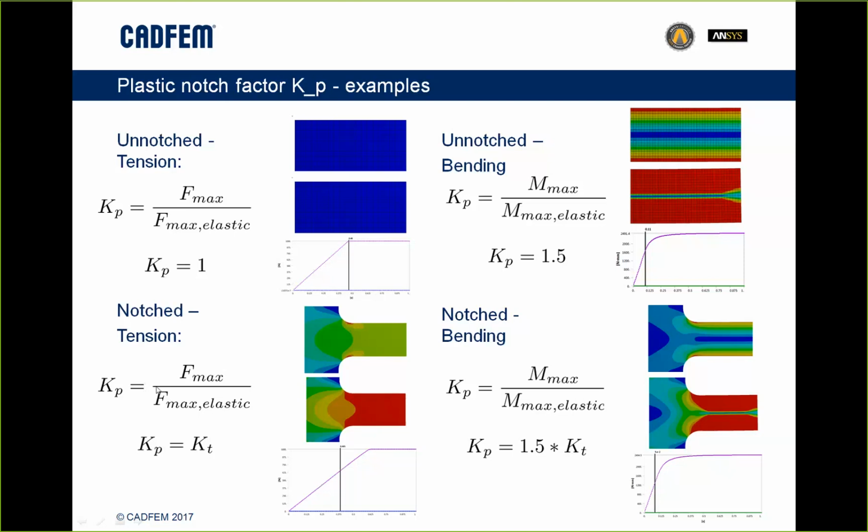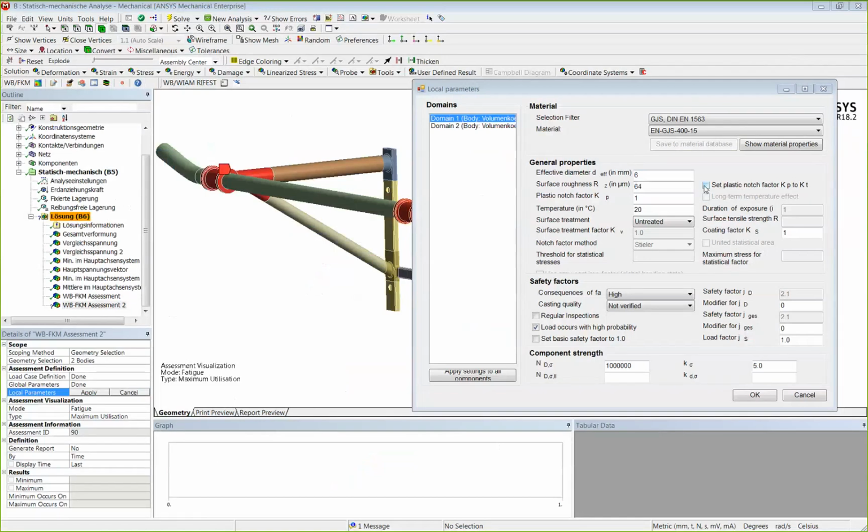I cannot directly say what it is. What I could do is say that in most cases it's equal to the notch factor, and the tool has a possibility to set that as the notch factor. Or I can say there is one value I test against. So I really calculate linear elastic ideal plastic, and I calculate until the calculation fails. I would not recommend that. Or I test until a value where I say, okay, that's the value I need, and I don't need any more. In this case, I tested against the value of 2. I calculated the force where it plastified at the first point, increased the load by a factor of 2, and saw that my structure was still converging. So I don't know how much I could actually put on, but I could put on more than a factor of 2.